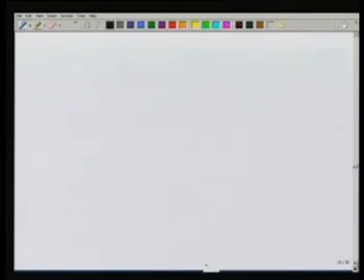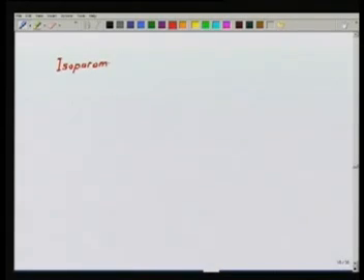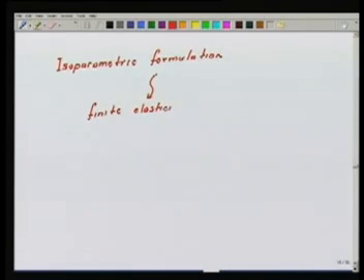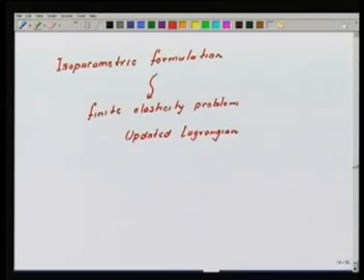A place where this isoparametric representation naturally comes in, and is normally used, is when we do the nonlinear elasticity problem, the finite elasticity problem, using what is known as the updated Lagrangian method. Those things we are not going to discuss here, but in the case of finite elasticity problems, isoparametric formulation becomes almost mandatory. Naturally it has to be used because of the very way we are defining deformations there.